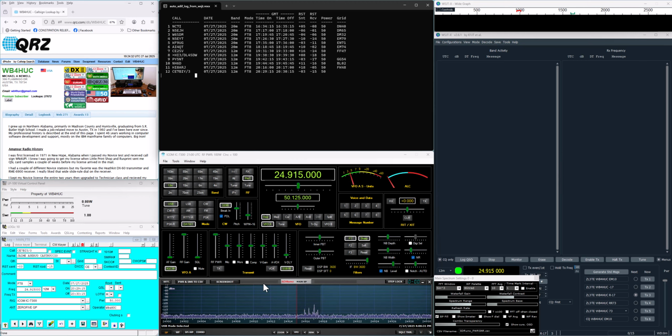So the receive antenna connection on the 7300 is brought out to the back panel, and the antenna connector for the separate software-defined receiver is connected to that antenna connection on the back panel of the 7300. So that's where the separate little receiver gets its RF signal from. And then a piece of software called SDR Uno controls that separate receiver and provides the pan adapter.